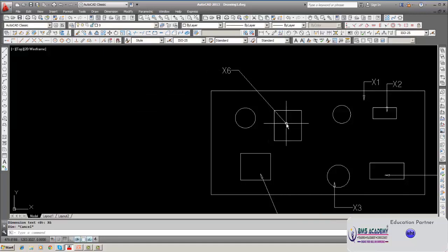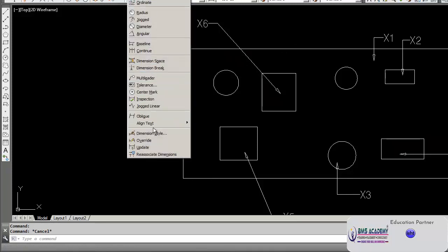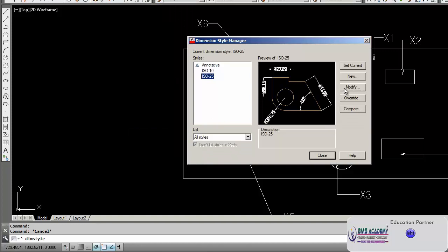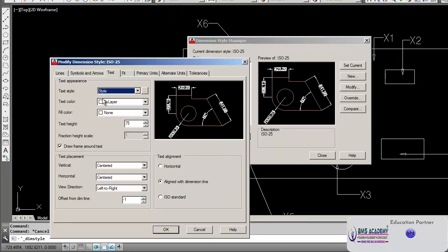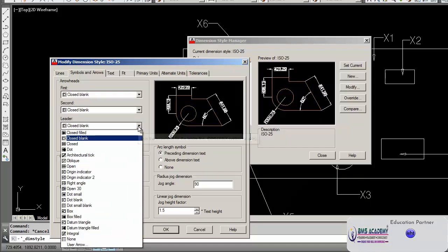These arrows you can select the way. So before dimensioning, you have to select the arrows. Okay, these arrows you can select. See here, what we have done. This is the case with the style. Let us see what is there in the arrow mark. Style. See, this is leader, closed blank. In leader there are three things. First, second belong to straight line dimensioning. Third one is closed mark. So if you want to change that, you can select. Normally for part naming you can take dot.